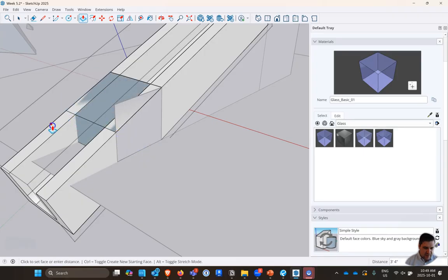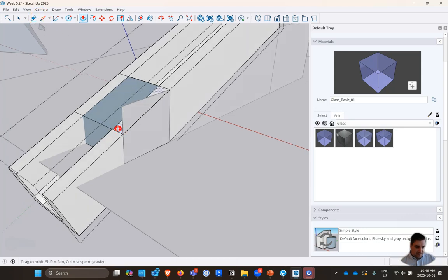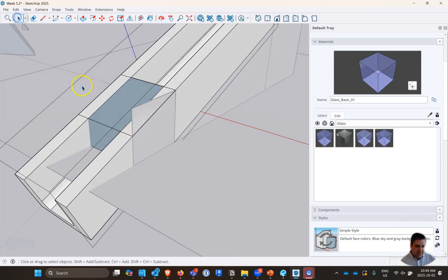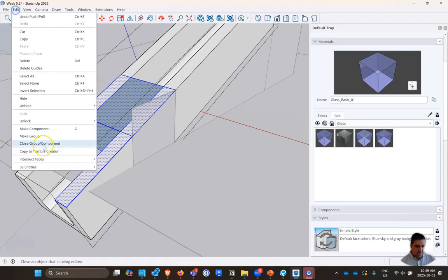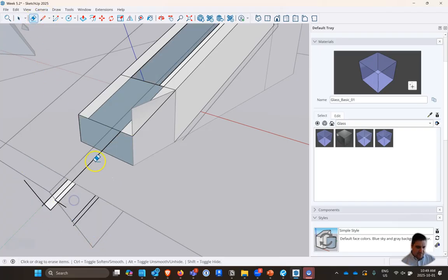I'm going to extrude that through our shape like this. And let's use the intersect tool just to make sure we get all those intersecting lines. And yeah, it should work. I'm just trying to think if I had everything. Intersect with selection. And now we can just go through and kind of delete a whole bunch of stuff here.